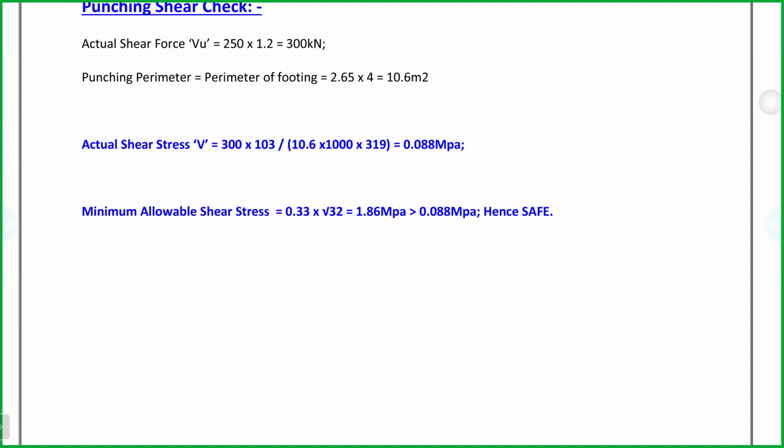Sir, why can't I go for more than 20 centimeters? Good question. Again, who is running the show? The foreman and his crew. They won't always measure 10 centimeters, 20 centimeters, 15 centimeters. By eyesight, once they place some of the rebar, they can place the other rebar as well. They don't measure every single rebar. It's not possible, because slab-to-slab cycle is 5 to 6 days. If you measure each and every rebar, it will take more than a month. It's not feasible.